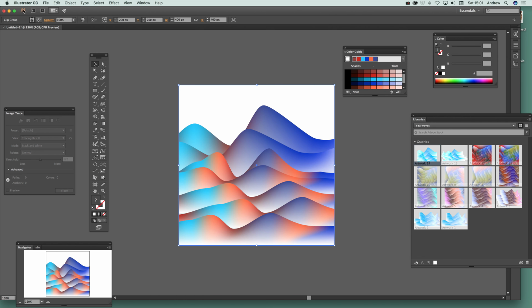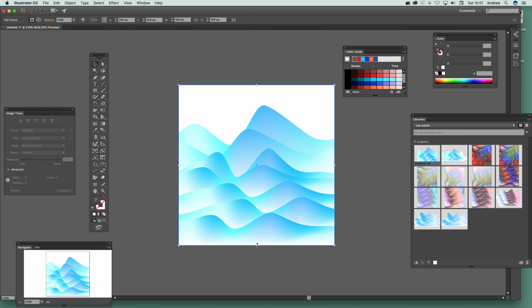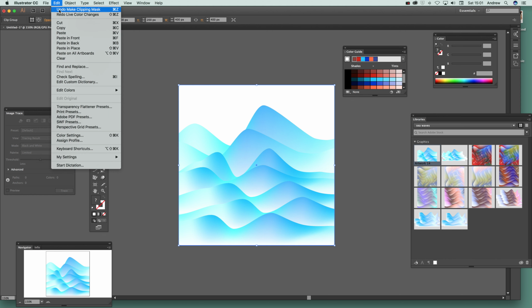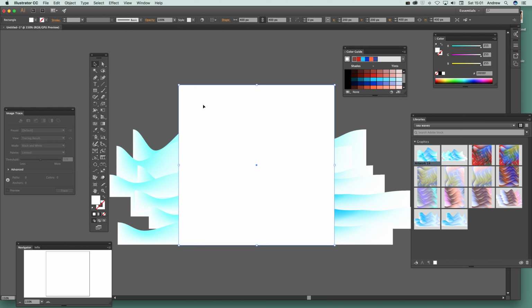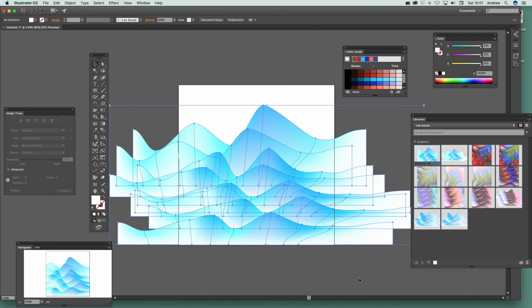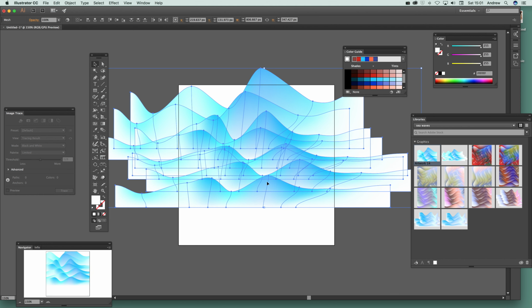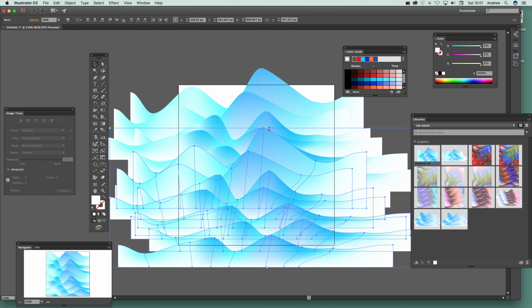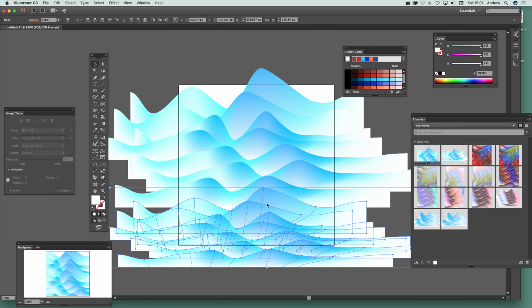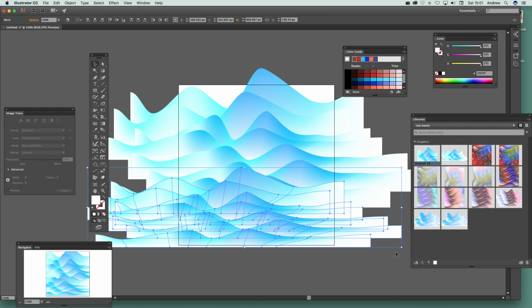Now, I'm not going to stop there. I'm just going to undo that. Don't want that, because what you can do, and also I'm just going to remove the clipping mask. I don't want that. So undo, make clipping mask. Just wanted to show you, you can do that. You can actually just select the lot, and then hold the Alt, Alt Option key down, and then just resize that. So you can create one batch and then create some more.